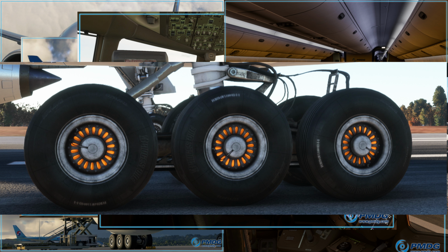Now, going on then, the anti-skid system is active in all braking modes and assists with skidding and hydroplaning. Each wheel is monitored on its own and controlled independently. To complete the anti-skid system, from wheel speed sensors to regulating valves and control logic, pretty much all of that stuff is modeled.